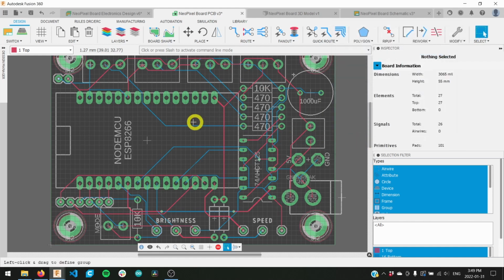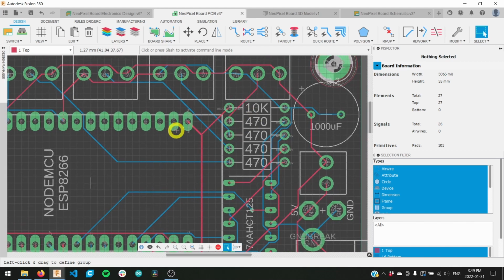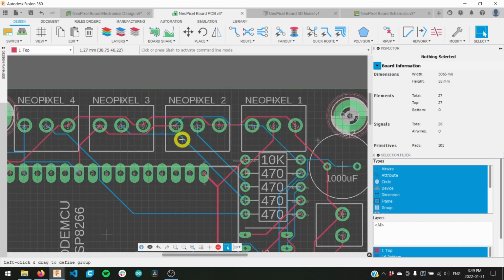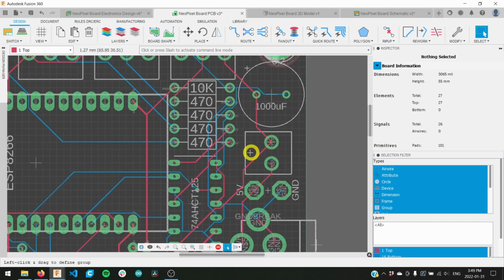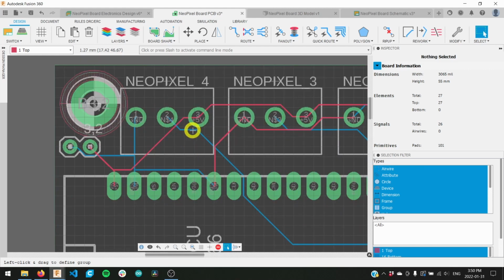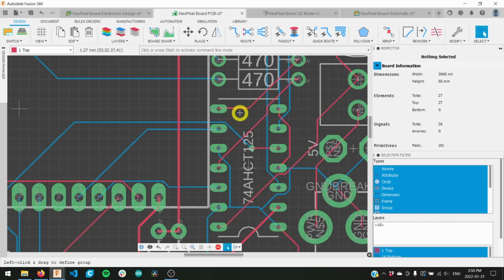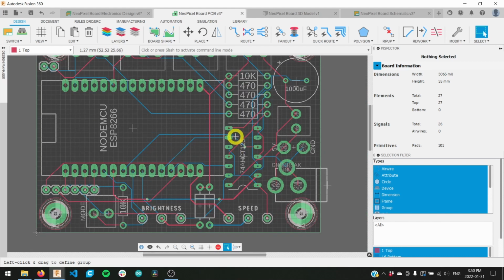However, there are some limitations to using the autorouter. In particular, it's not able to optimize the location placement of the components. You can see it didn't test out moving the components around, it just left them where I already had them placed. If I move these components around, I may actually be able to find a more optimized solution. And it doesn't really care about the overall aesthetic value of the traces. You know, it doesn't try and beautify your board layout at all. I'm not going to get up on a high horse and say never to use the autorouter, especially because my trace layout is far from optimal or graceful in and of itself.